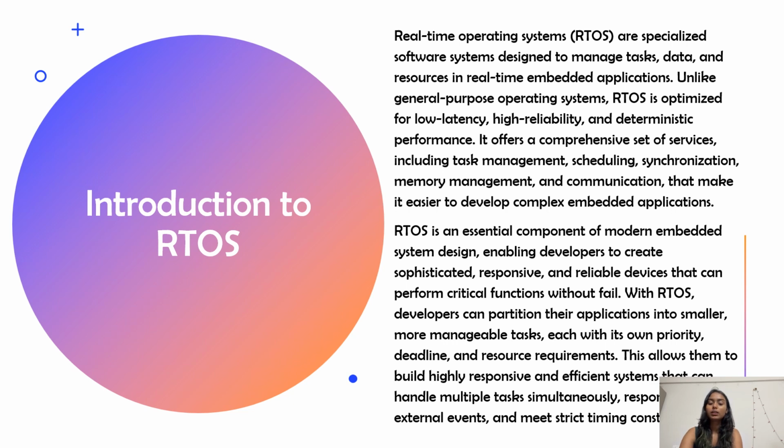RTOS is an essential component of modern embedded system design, enabling developers to create sophisticated, responsive, and reliable devices that can perform critical functions without fail. With RTOS, developers can partition their application into smaller, more manageable tasks, each with its own priority, deadline, and resource requirements. This allows them to build highly responsive and efficient systems that can handle multiple tasks simultaneously, respond quickly to external events, and meet strict timing constraints.